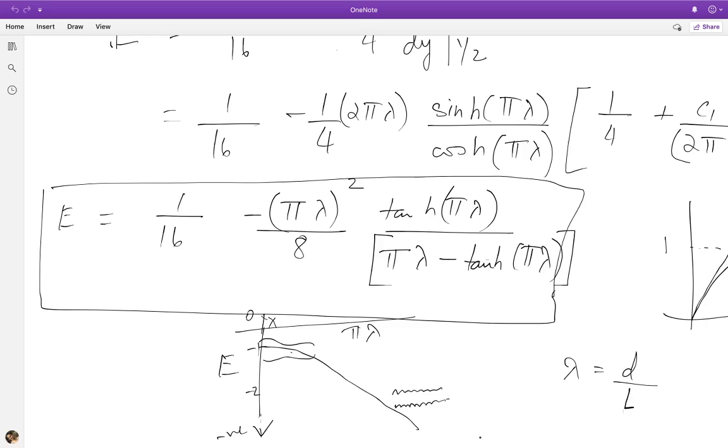So with this in mind, when you encounter other problems where it seems like the domains are complex and you know that you could solve the problem if only the domain had a simpler form, well then simply represent the complex domain as a perturbation about the simpler domain and then carry out a domain perturbation. Now in this course, we won't spend more time on such problems, but one would also encounter this idea when dealing with deforming interfaces, provided the deformation is small. Again, we won't do that in this course because we're focusing on single phase flows, but it is a powerful idea that you will encounter again and again, which is why I thought it would be nice to introduce it at this point.